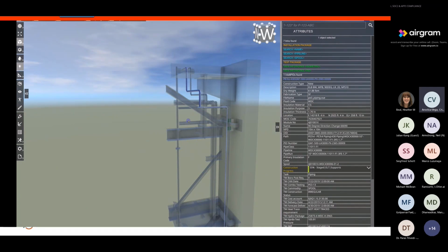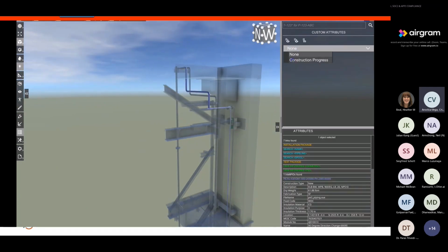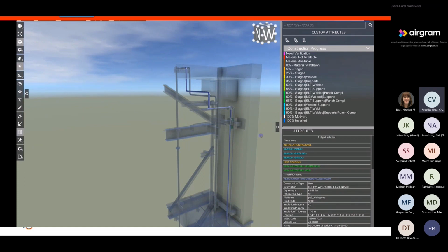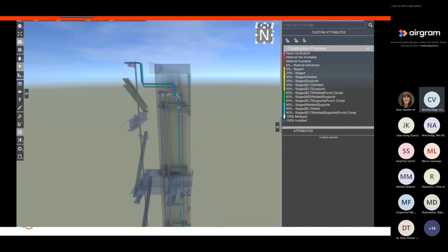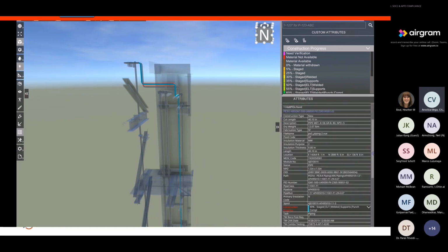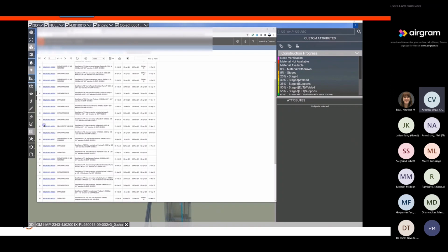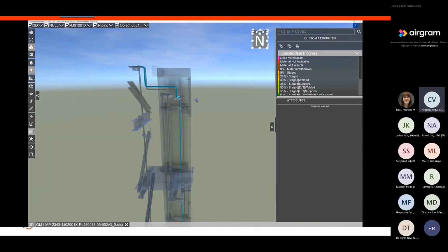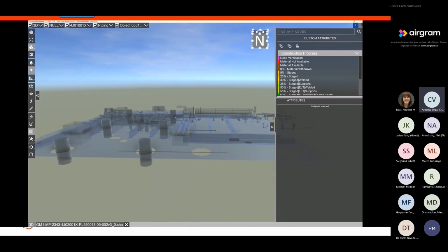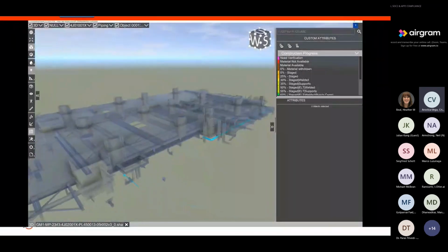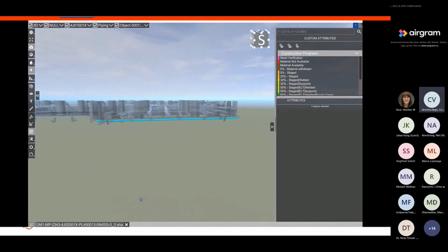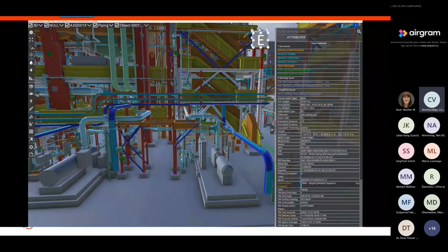In this case, I'm also adding the simulation for the construction status progress, so we can visually see the color coding per startup system, per construction color, or per any kind of definition. It's really simple to define the color. You can see there, the attribute was there. If I open a second IWP, I don't need to close the model. The model will automatically feed to the second volume by the hyperlink condition definition. You can see there, I'm visualizing the second IWP. We can define if we only want to see a piece of pipe or anything.